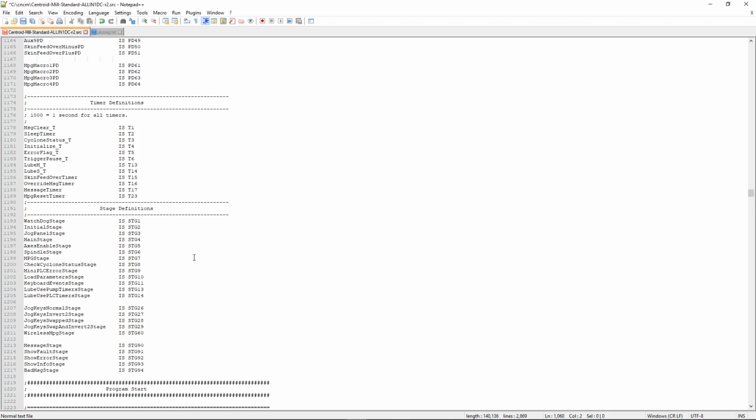You should also be aware that if you have certain stages that don't get turned on, a lot of times when you're going to troubleshoot, you may have logic that should be turning outputs on, but all of a sudden you see that nothing is happening. You'll see in the PLC detective, which we'll go over later on, that if that stage isn't on, even though all the conditions in that logic have been met, the PLC program is completely bypassing it.